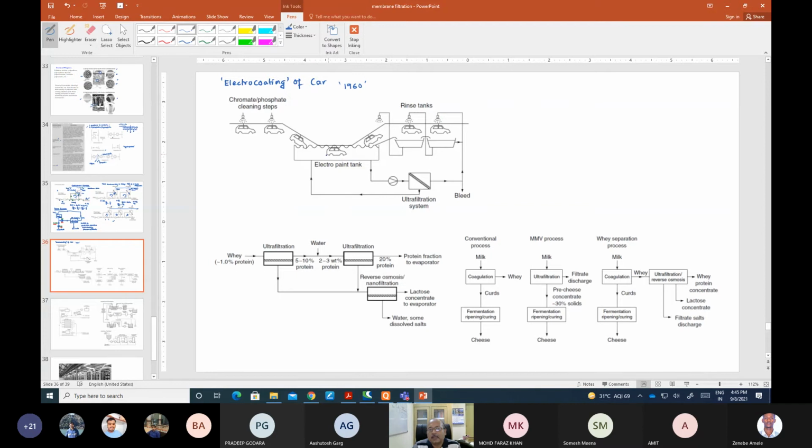Those particles which are negatively charged migrate towards this positively charged electrode and get deposited on it. Because this is electrodeposition, the deposition is very smooth and nice, and you can control the voltage and have a coating over the entire surface of the metal part. Then you take it out, but you will have some extra paint that might be there due to surface tension or otherwise.